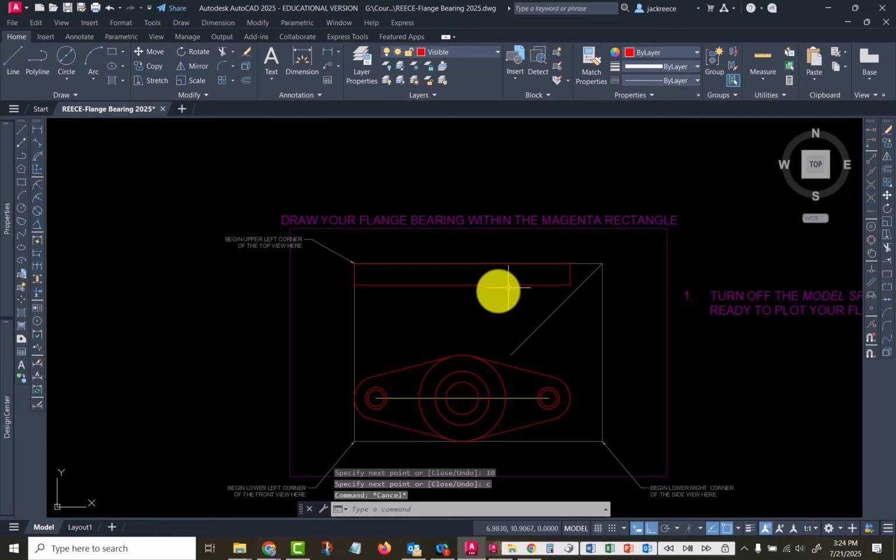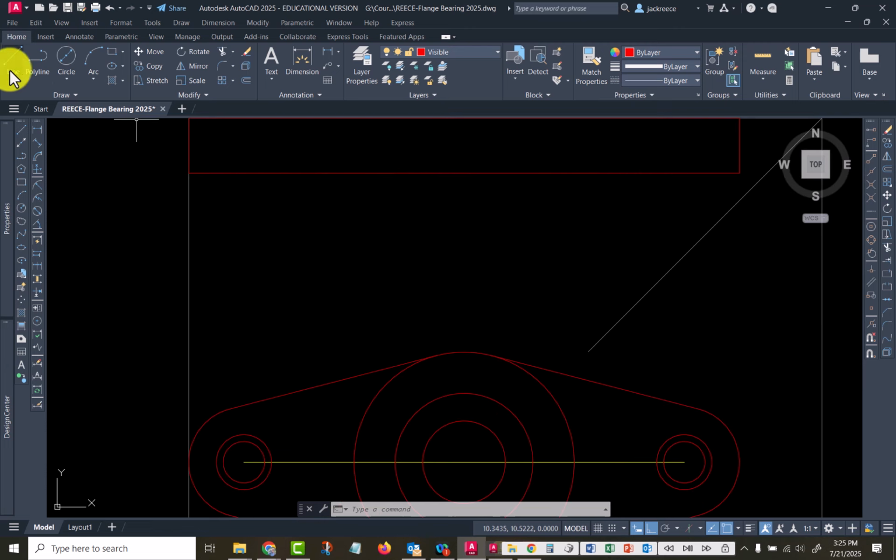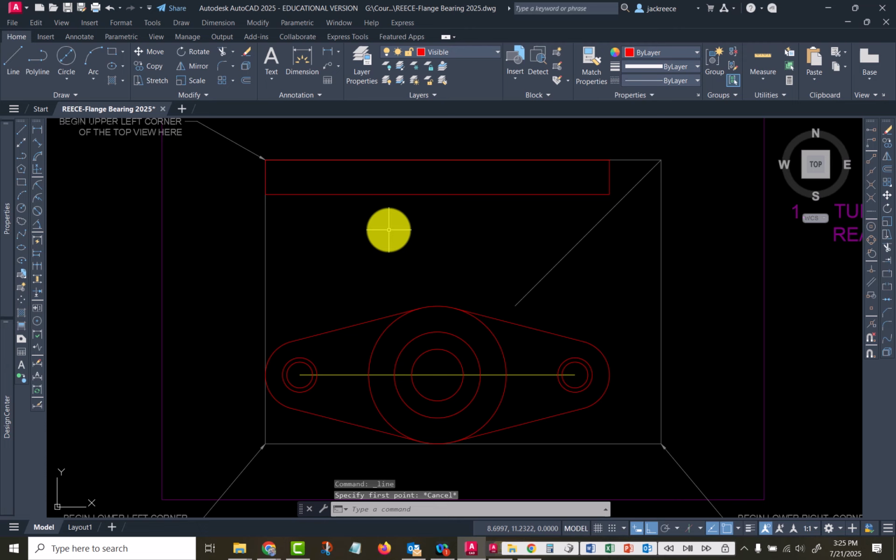And so that gives me the side view of the base of the thing. Now we got to add in what would be the cylinder. And so I'll go line command, and my OSNAP tracking is on, so I'm going to hover over here, bring it up. Oh, I didn't get my depth, sorry.